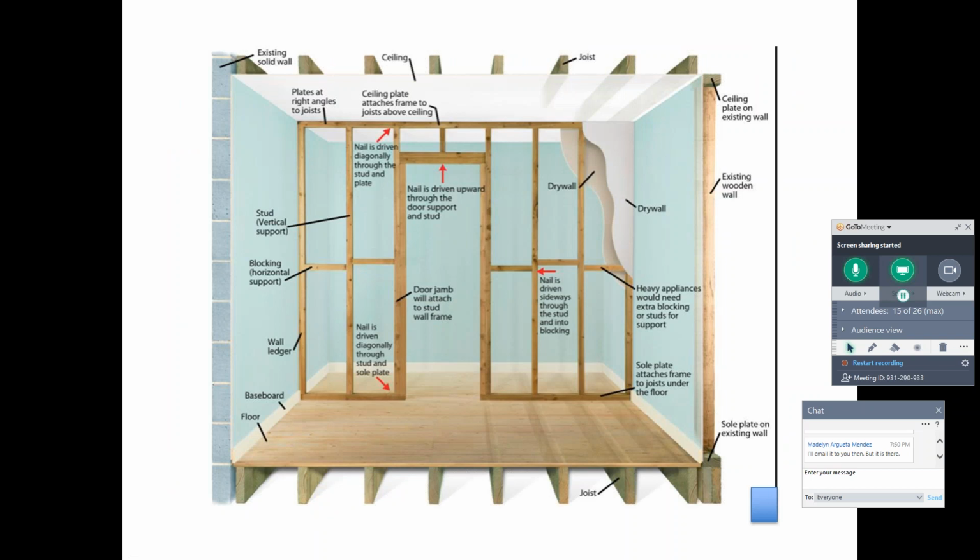So I wanted to add another visual so we can think about how walls are built, since we're dealing with building systems as a whole. I think people get really freaked out by wall sections when I make them do them in all my classes. So just remember, it's pretty simple. With the floor joists at the bottom, it's just wood, a subflooring material. On top of that floor, so this is the floor in this case, right? If you have a hardwood, it might just run right over top those joists. We might carpet over the hardwood or plywood boards if we don't have hardwood existing, or tile over that, right? So it's pretty simple to draw the floor cutout of this section.